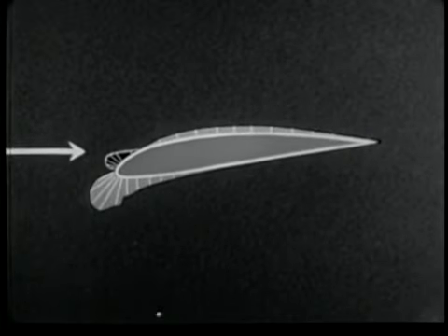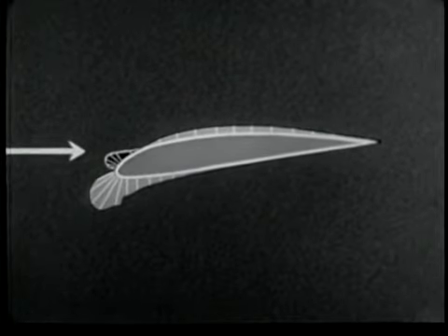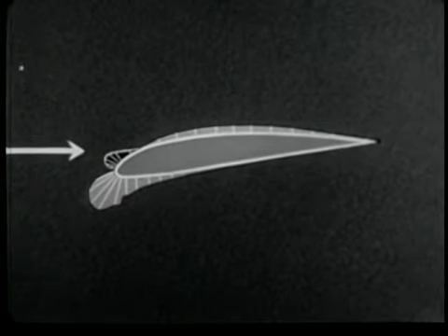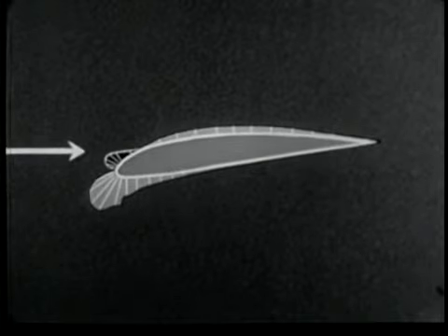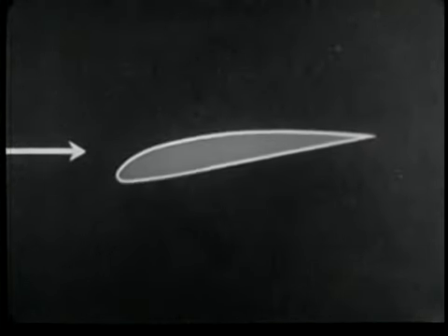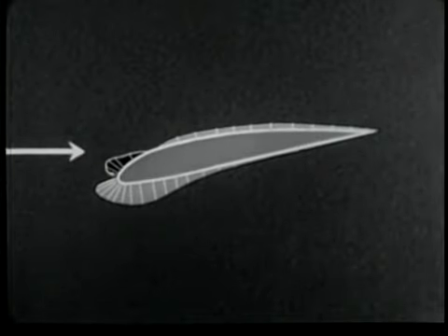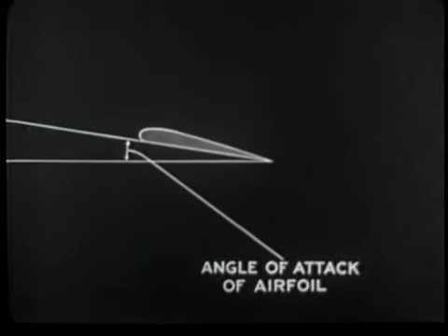The negative pressure on the upper surface of the wing shows little change. However, the negative pressures along the lower surface begin to increase at the leading edge. Further increases in this area, accompanied by very slight changes in the positive pressure bulbs, are the only differences which are readily observable as the angle of attack is further decreased.